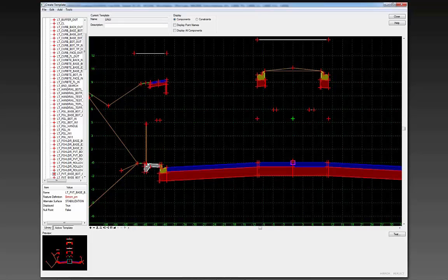So if they've got to cut out the ground for the sidewalk, they're going to find out what the sidewalk lines are on the proposed, and then all they have to do is tell their graders to go 4 inches below the top, and the blade will cut out for the bottom of the sidewalk. And the same thing for the base and for the pavement. So they do a depth from top of surface is what they're doing. So we don't even need to worry about these bottom points.